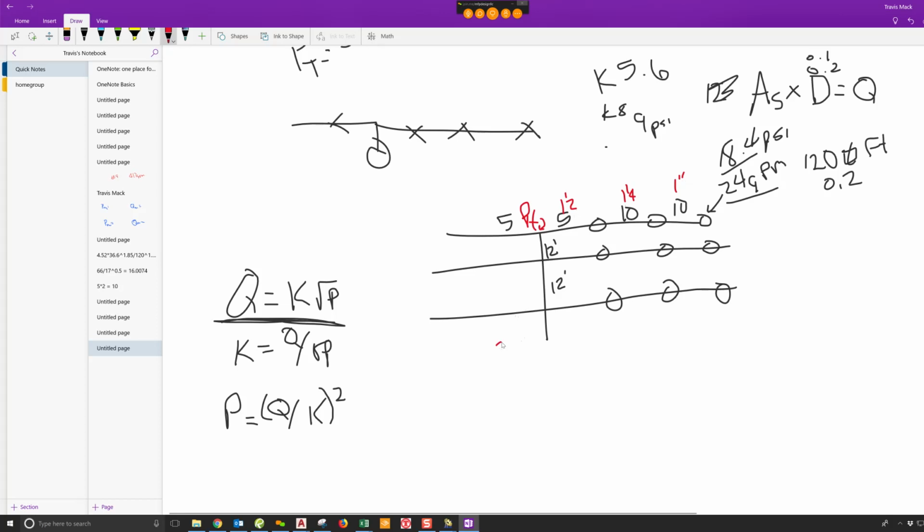And for grins, we'll say that this is 3 inch for the main. We're going to assume that everything is schedule 40 right now. It just keeps everything simple. If we do this again and go into more depth, we'll go over what you do when you've got schedule 10 piping. You've got to figure out different equivalent lengths, or if your C factor changes, things such as that. So we are using black steel and it's wet.